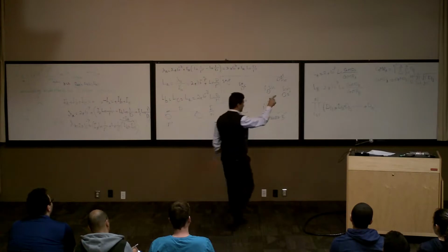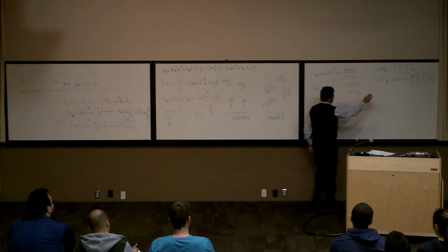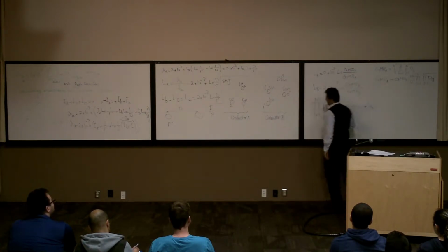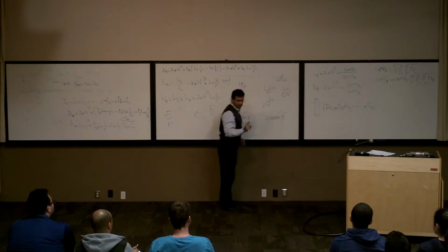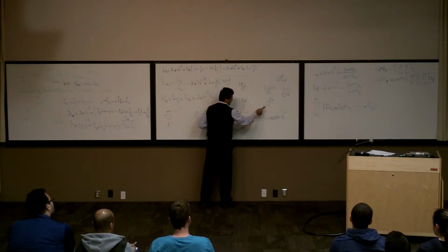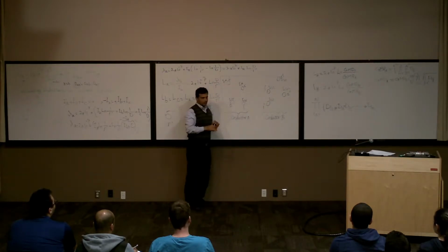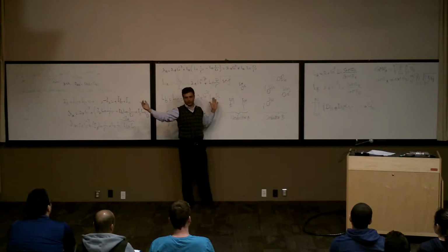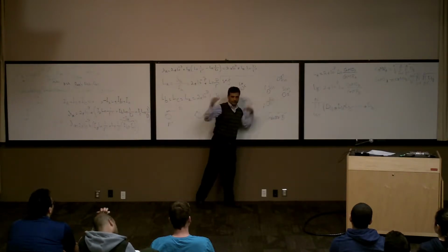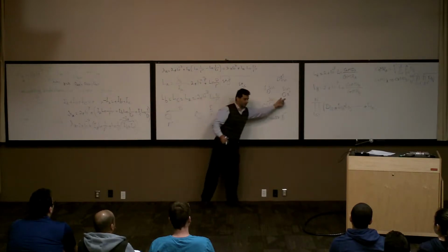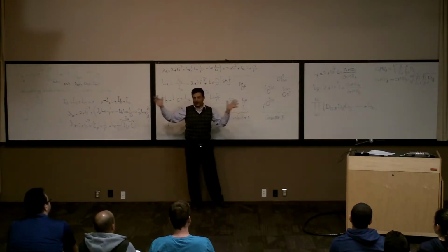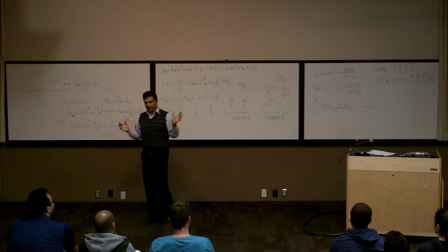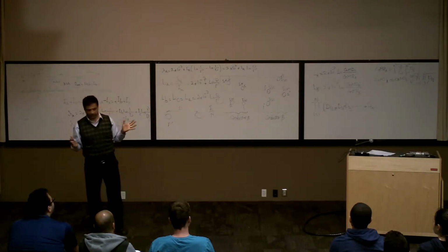So here, now the next term, if you look at it, GMD is coming from here. It said, okay, if you can put it the same way, go this one to this, this one to this, this one to this, this one to this. Consider one conductor from here and go connected to all of them. Calculate the distance and multiply by each other. Next one, the same thing. Next one, the same thing. And you add them all together. This is how we calculate GMD and GMR for this system.